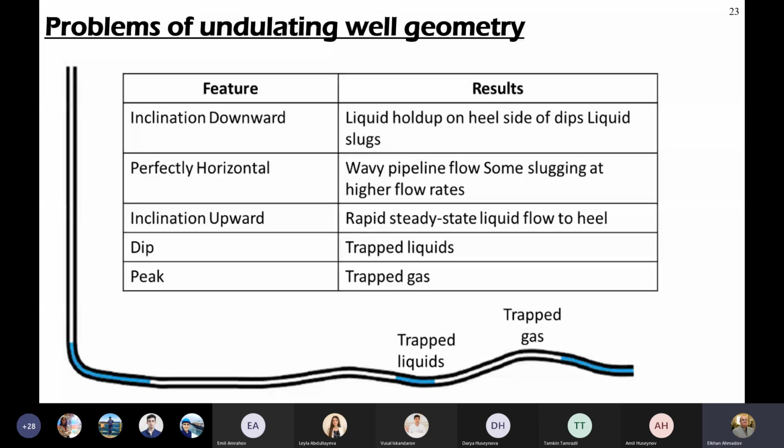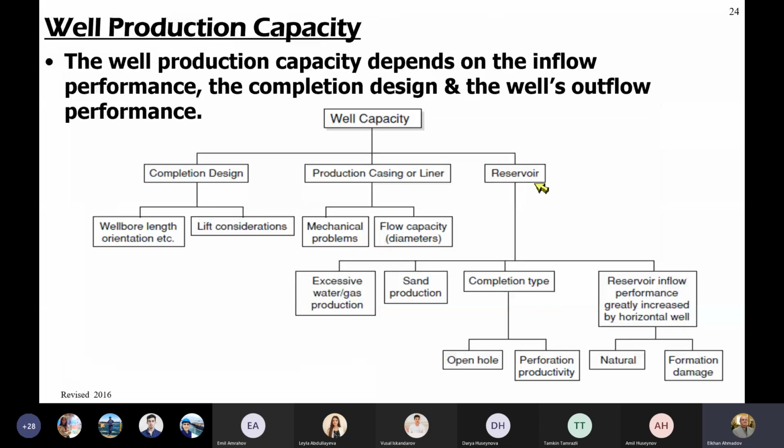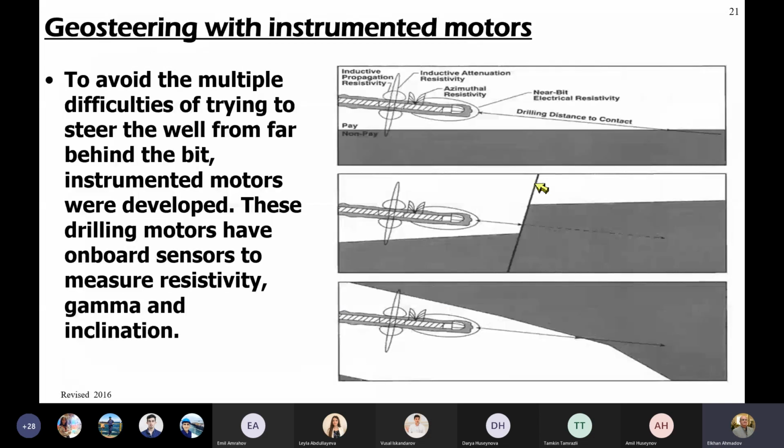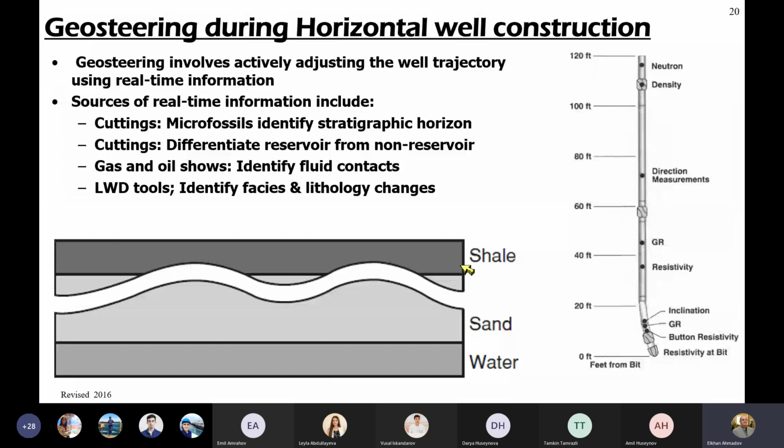The next question was about why it is desirable to steer a well just under the shale that seals the reservoir. The reason is, when we have shale here, this is a ceiling formation, and we have no fluid to flow into the wellbore from it.